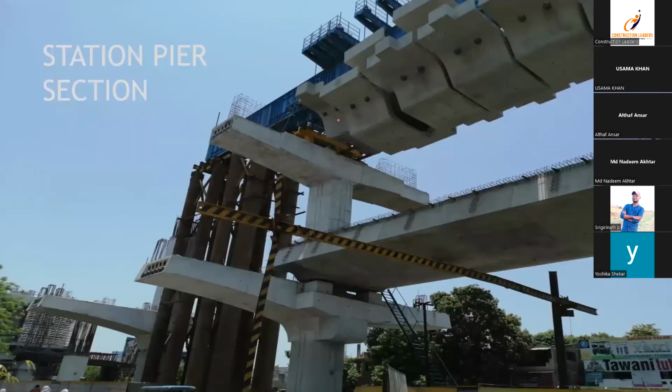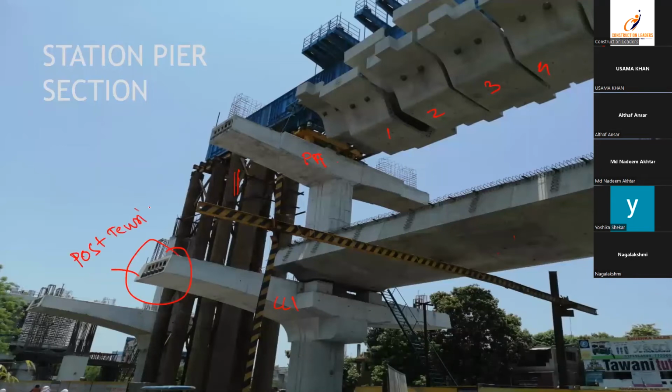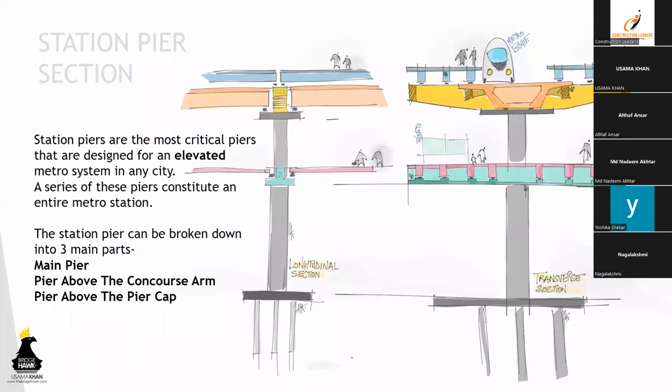So this is a typical segmental launching. You can see segments are being joined and lifted one by one. This segment is already cast, and this is the staging arrangement. So this is concourse arm 1. This is, I believe, a platform arm. Over here, if you see, this is entirely post-tensioned. Since we are talking about huge moments, it is imperative that we go for post-tensioning. So this is typically a sketch to throw some more light.